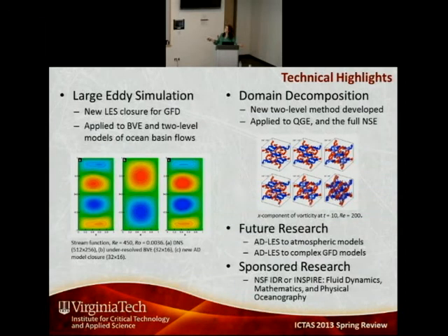If you look at the bottom row, however, this is a little bit different. This is changing the resolution of both fields. Here we've got 128 cubed and 128 cubed, here 128 cubed and 64 cubed, and here 64 cubed and 64 cubed, and you can see that a lot of error comes into the calculation at this point. It's under-resolved, right?